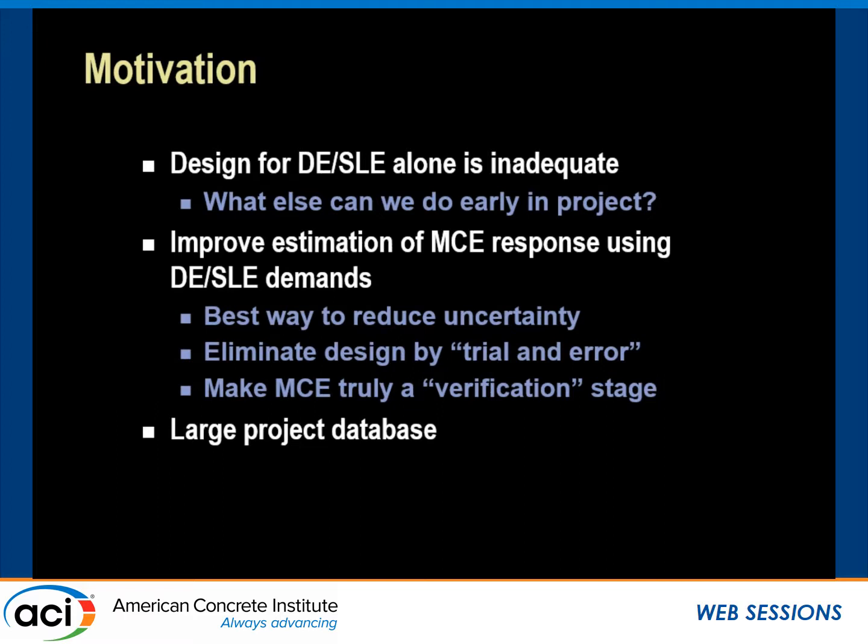The best way that we can reduce this uncertainty in the prediction of the MCE loads is by looking at past projects and seeing what the actual amplification has been. By doing this, we can cut down on this design by trial and error, and we can also make the MCE process truly a verification process rather than a design by trial and error. And then the third motivation for us is that we've done a lot of these PBD projects, so we have access to a pretty large database of past results, and we can mine data out of there to use for the study.